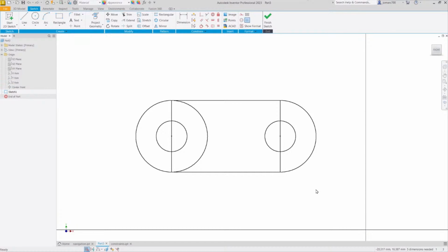Now that we have the target shape of this sketch, from here, we can now add dimensions. Once more, take note of the color of our sketch entity. Let me turn on our sketch constraints, hitting F8. Let me hover over the circle, left click and hold. Notice we need to define the diameter of the circle.